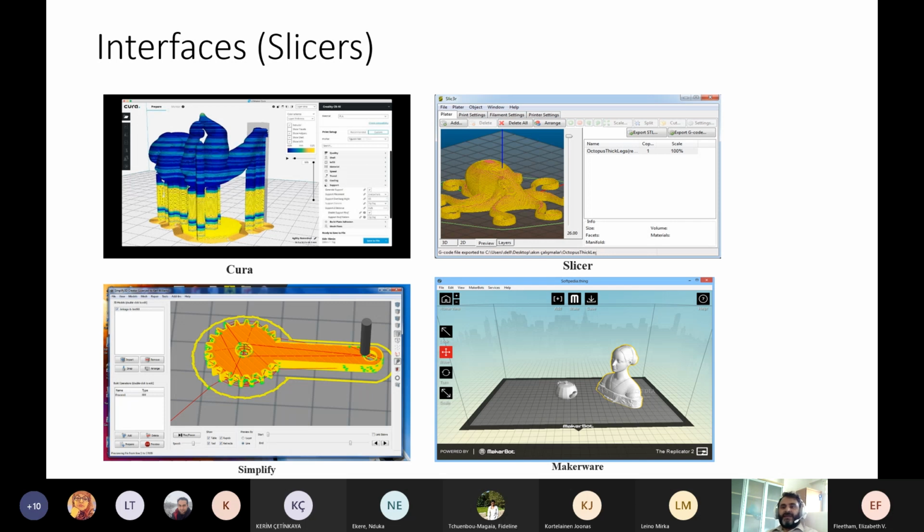After being created on a digital platform and saved in STL format, the project is transferred to the 3D printer's control software. In this software, the part is divided into layers. The production plan of each layer is then made. There are various three-dimensional object slicing programs used in the market.